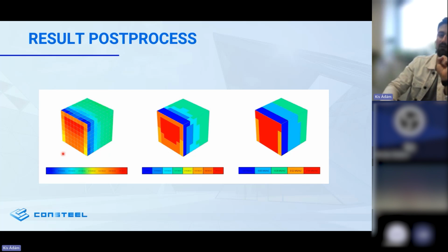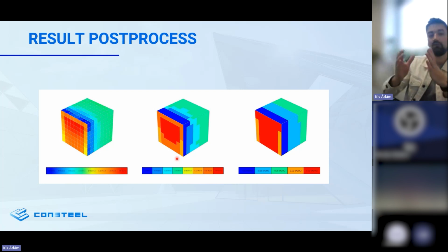But if we'd like to post-process these results, we try to reach several zones with larger surface loads, which try to mimic the zoning procedure of the Eurocode. Therefore, they will be comparable with the Eurocode, because we will obtain larger, obviously much more conservative loads, but based on the simulation results. So it can be used for almost any type of building.